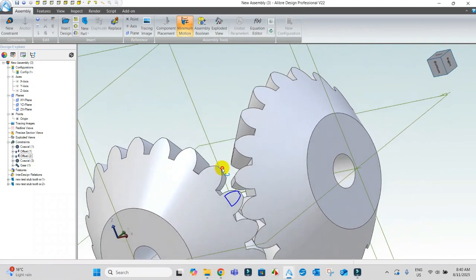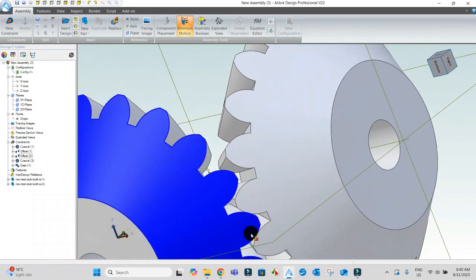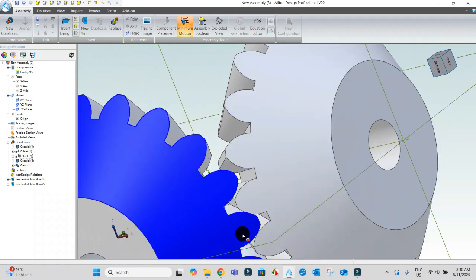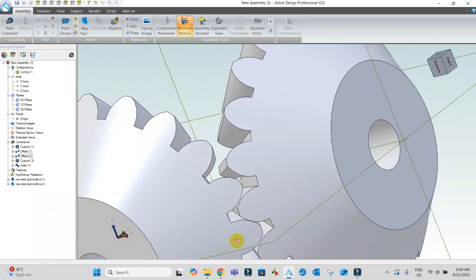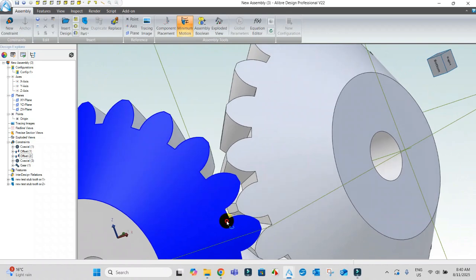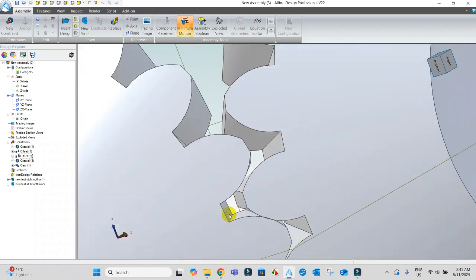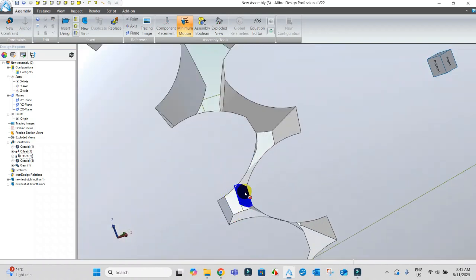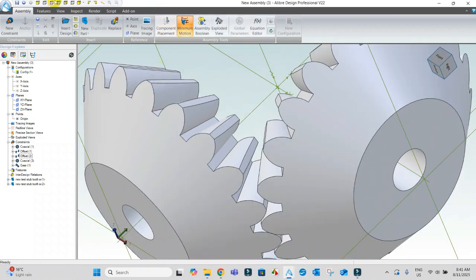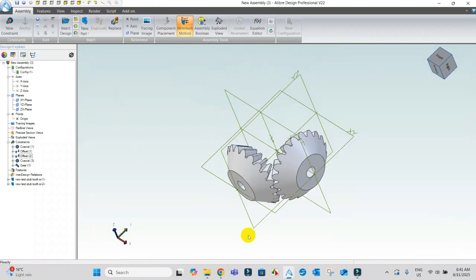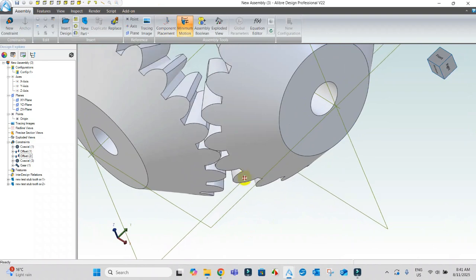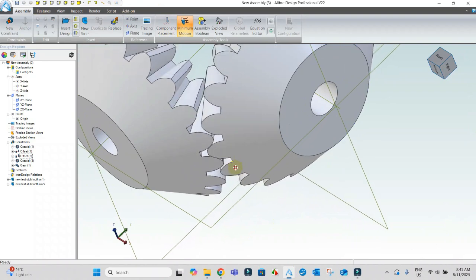We'll flip this over. And you see here, the compromise is now we have almost like a knuckle tooth form here. There's not terribly much engagement there. You see that taper I talked about in the previous videos, of course, that's getting deeper and deeper. But you see the engagement here. I can go a lot longer with the face of my tooth. It looks like my engagement position, the teeth are somewhat longer.